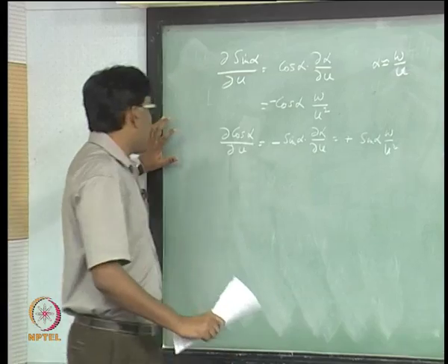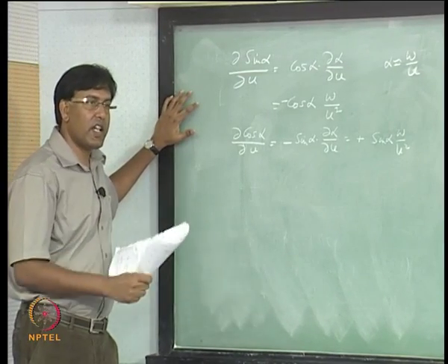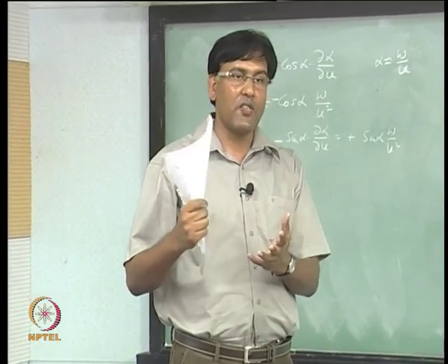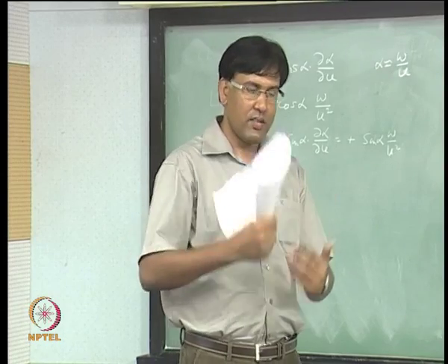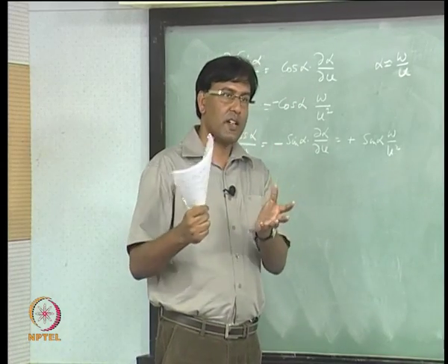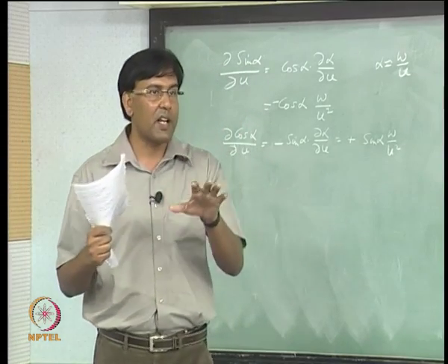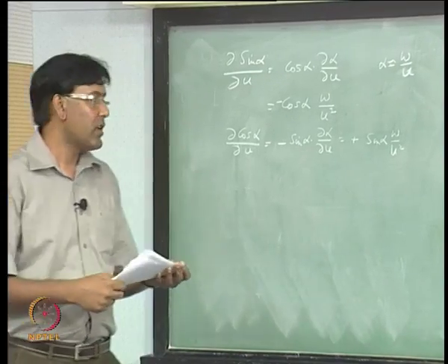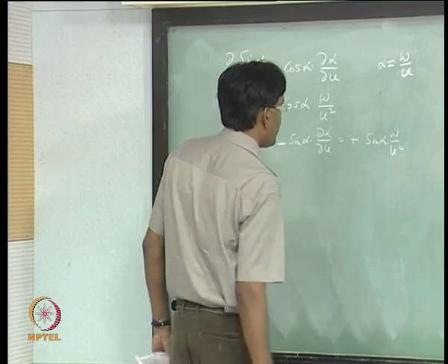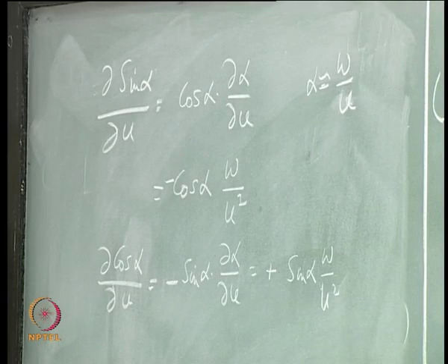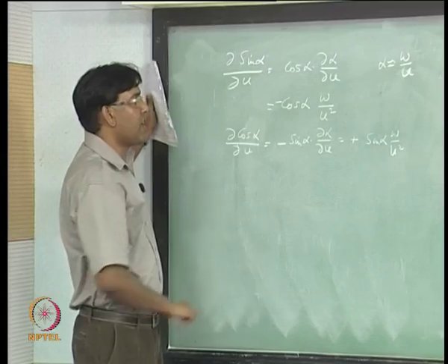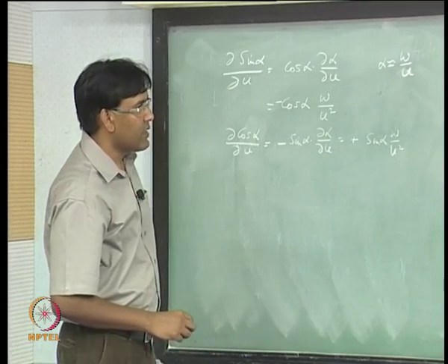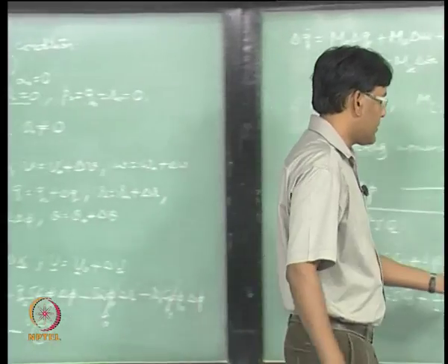okay. Now as I said, we have to evaluate the derivative at the equilibrium flying condition, right, and actually that is how you are going to keep your model in the wind tunnel, isn't it. You are not going to give a motion to the model, you are just keeping the model static in the wind tunnel, and you are trying to measure the forces and moments, right. Okay, so now I am going to look at my reference flying condition and try to simplify this.